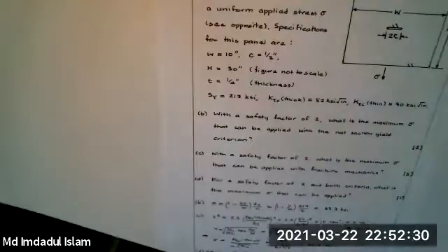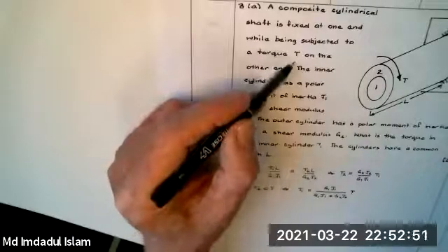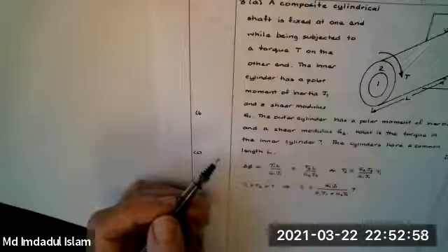Dr. Sinclair, I had a quick question about 3A. The question asked for the torque on the inner cylinder. So why wouldn't that just be the answer that you have for T2? Why wouldn't you just stop there? Why are you plugging back in for the overall torque and adding them? What you know is the torque T, the total torque T. That's what you know. And so should we give an answer in terms of something else I don't know? That's not the answer. Gotcha.